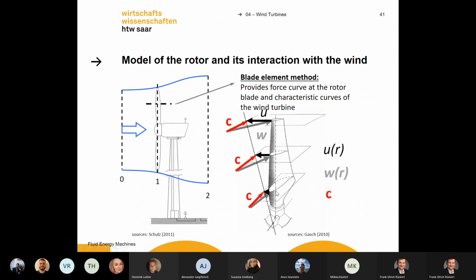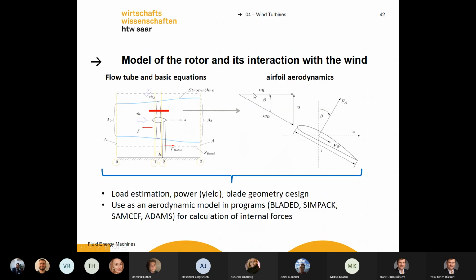Maybe look here slightly at this wing. You have to rotate the plate a bit to fulfill this velocity triangle, because the C value is more or less always constant. Again, here are our principles. It's difficult to calculate all the forces on the plates, and of course you don't do it with paper and pencil nowadays.